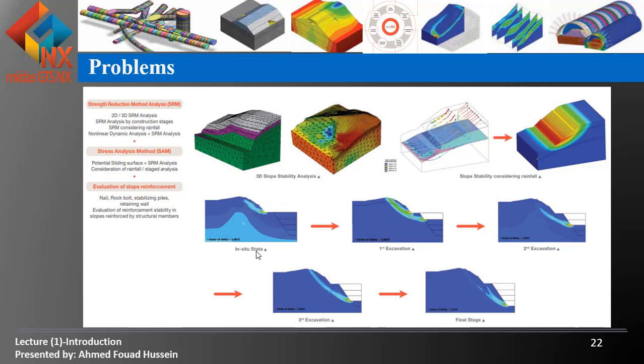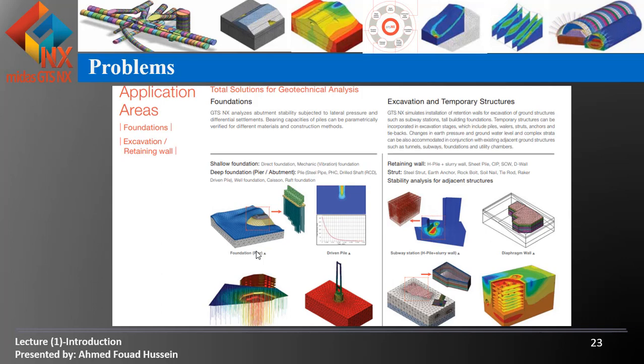So we study the quantity of water escaping in the dam, and we study the flow net, and we can even evaluate the slope reinforcement for slope stability, like nailing, rock bolt, stabilizing piles, and a lot of techniques.